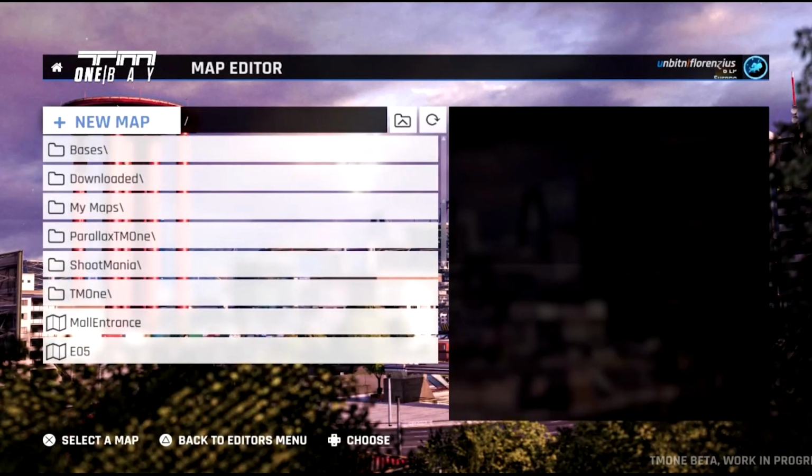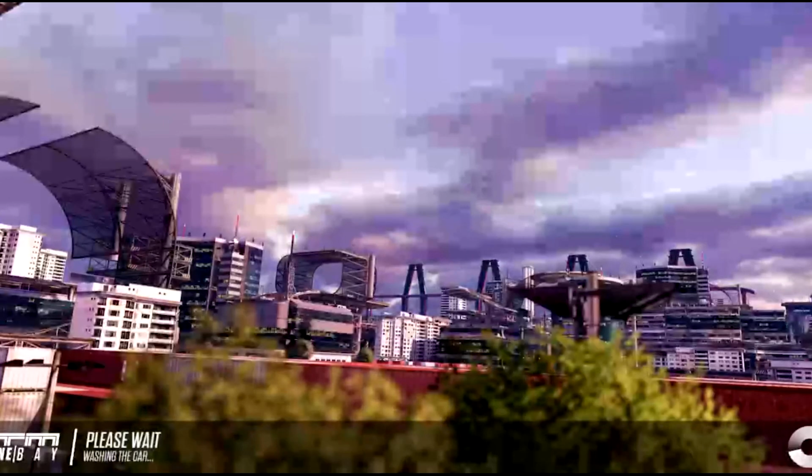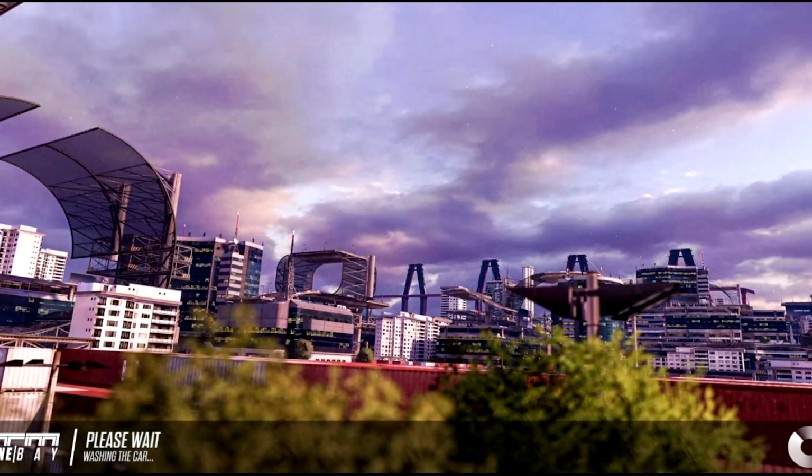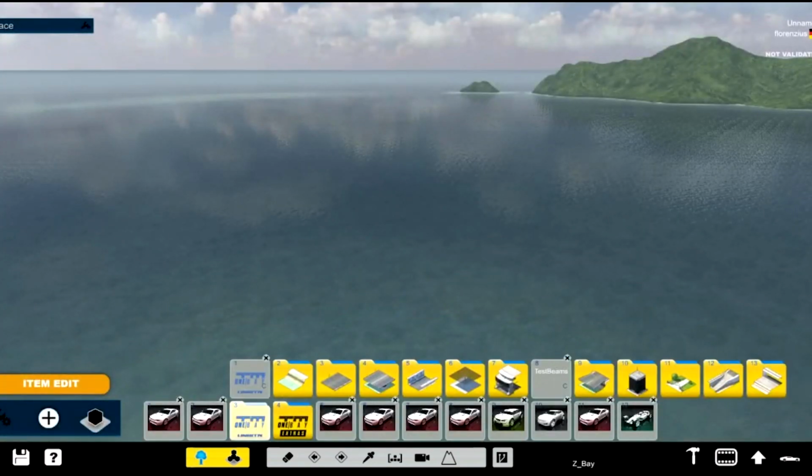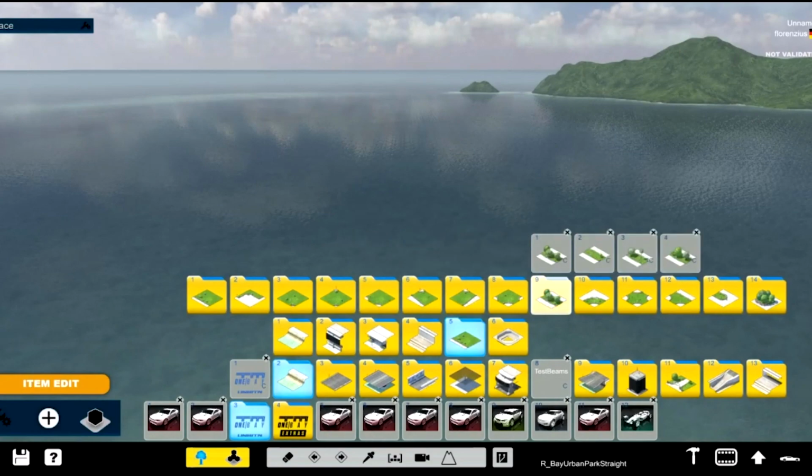And about the weird shadows, that's something we cannot avoid, sadly. We can counter it by creating a proper light map, of course, as I talked about. But the game at some point will always show some darker spots or some brighter spots where it's not supposed to be, because we are limited to 2048 pixels of light map space, and at some point that will not be sufficient. So let's quickly look into the trees.